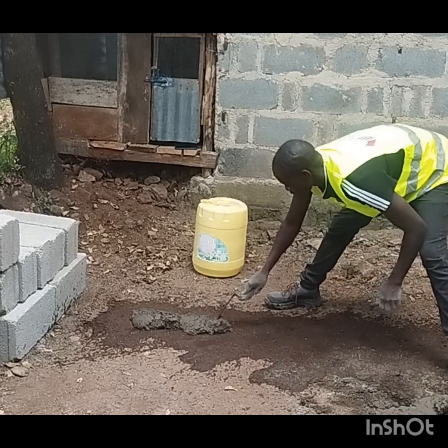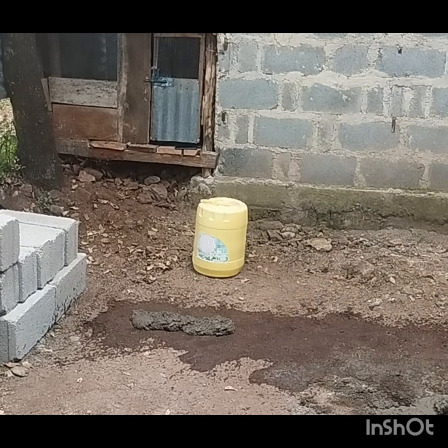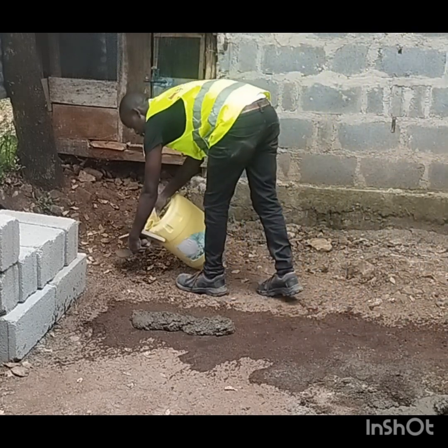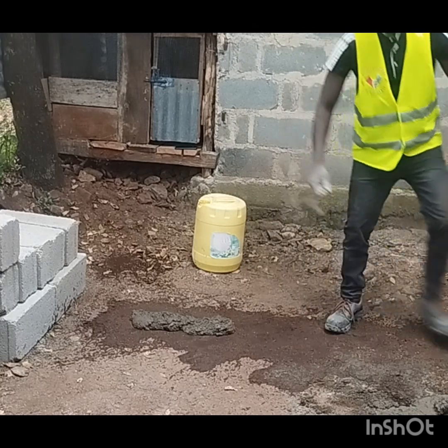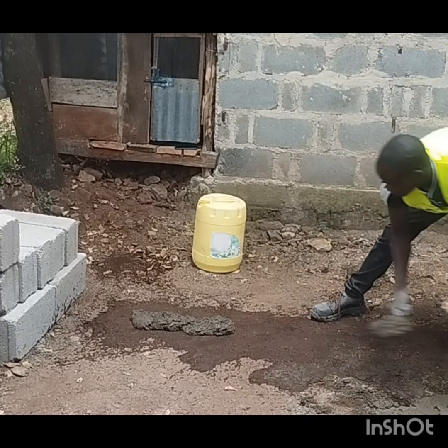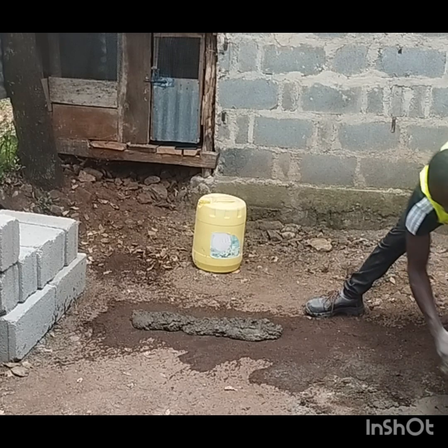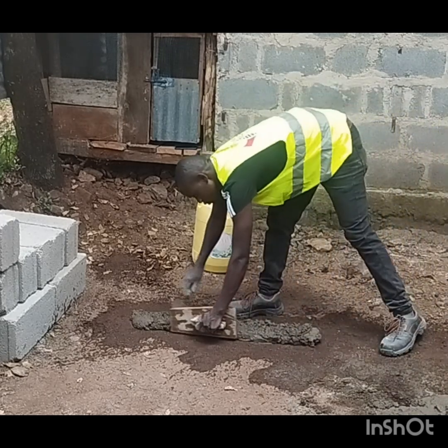So anytime you're building, whether you are putting a stone on top of another stone, or you are working on top of a slab, and even with plaster, you must wet the surface so that the dry surface doesn't pull water from the mortar, thereby creating air voids and later causing cracks.